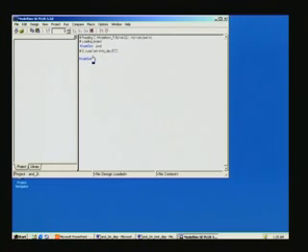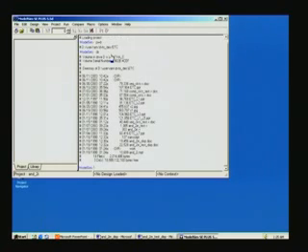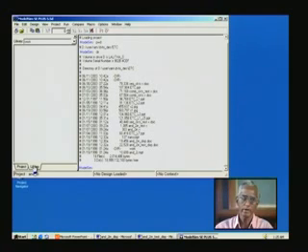So now if you want to see what files are there in this directory, you can just say dir. It lists all the files. Now let us see whether we have that and2in.v and its corresponding test. This is a test bench for that. So we have this here. Now the next step is, we have what is called project and library. You click on the library so that work is used here, right? And now what you have to do is